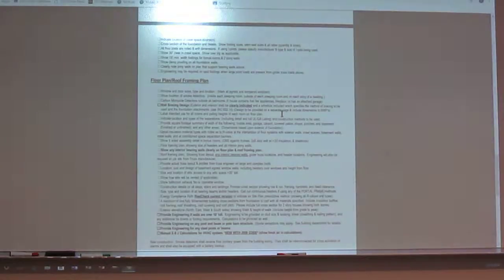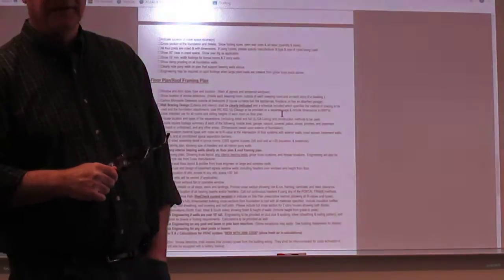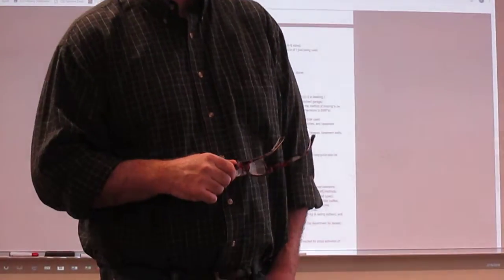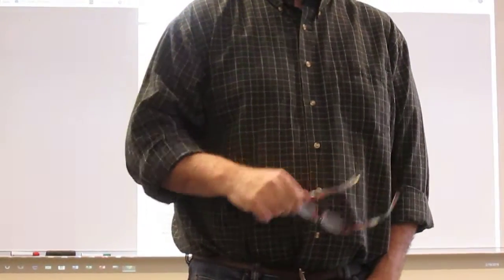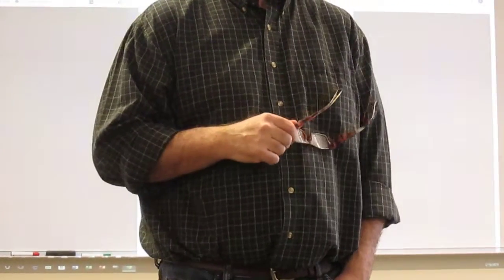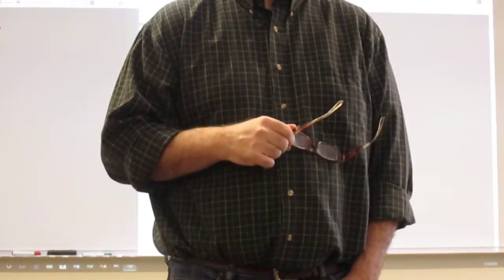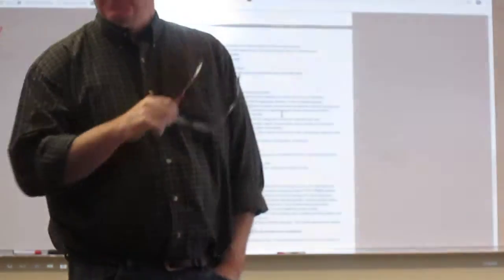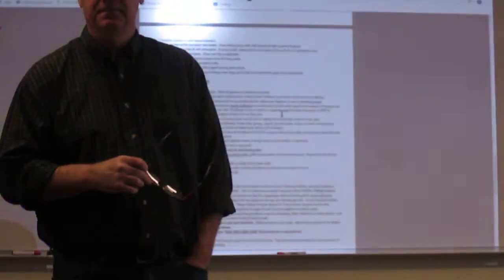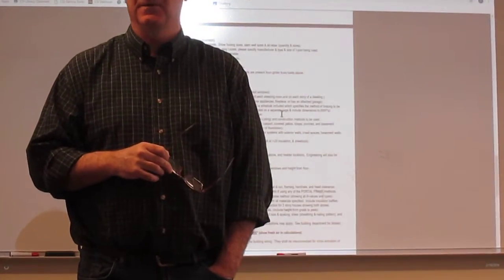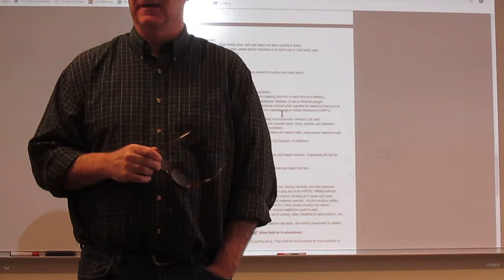If you go through the fine tooth of this though, it does tell you Twin Falls City requires 3 elevations in addition to these plans and the checklists that go on here. So they're all spelled out, every single drawing that they require, what's needed. So you might want to bookmark this or save this as a PDF. In essence, this is your outcomes assessment or what your drawings are held to. You will be critiqued to this list.